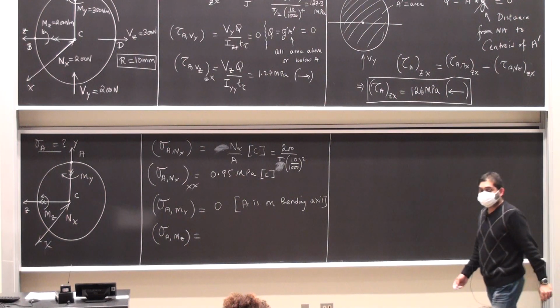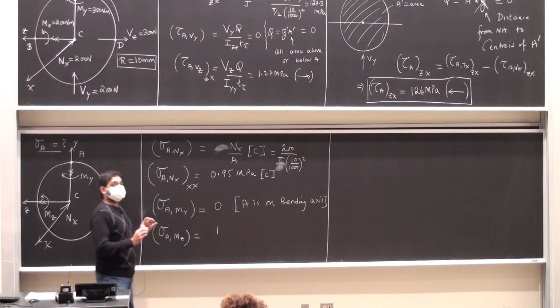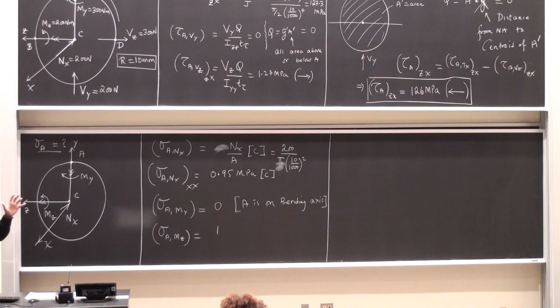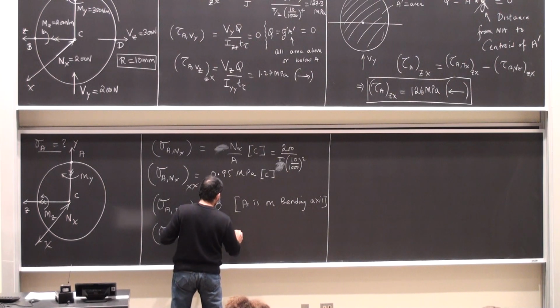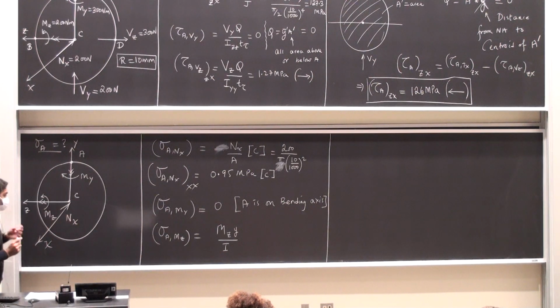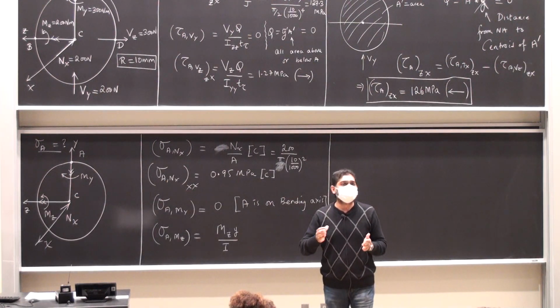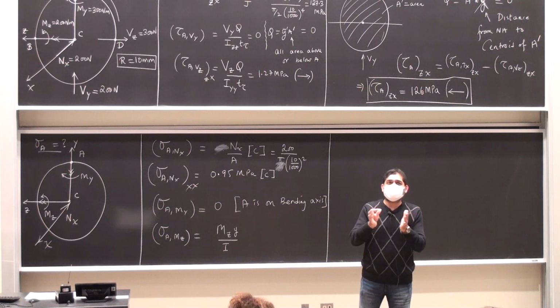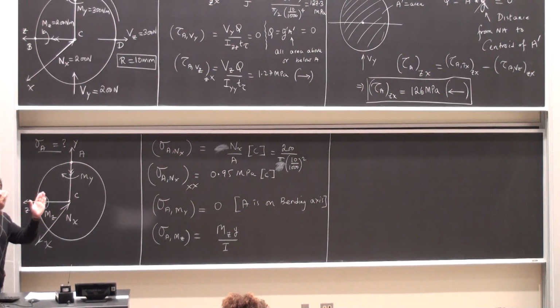Sigma A due to mz, I make use of the formula, okay? Because I know that first of all point A is not a point on the z-axis, so there is going to be some bending stresses. So this is mz times some distance by I. So watch this carefully. You will notice that I have not used the negative sign. When we derived the bending stress values, we said that it's minus my by I something, right? I am not using the negative sign because we are going to look at what the state of this bending stress is by seeing how the cross section is bent by the bending.